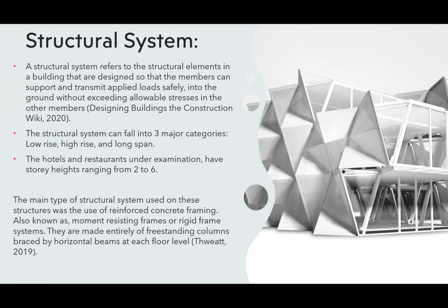This combination of columns and beams are designed to support horizontal and vertical loads using the rigid connections between each member of the frame, allowing them to resist lateral and overturning forces as well as allow for larger movements during earthquakes.